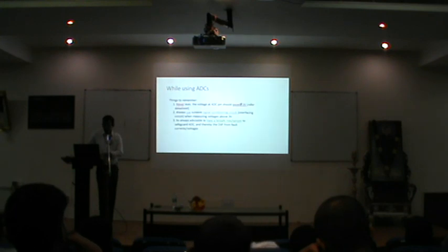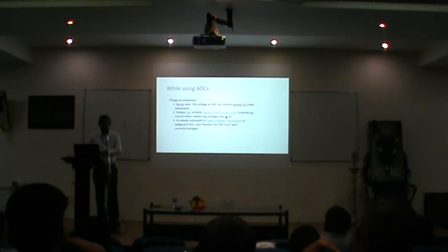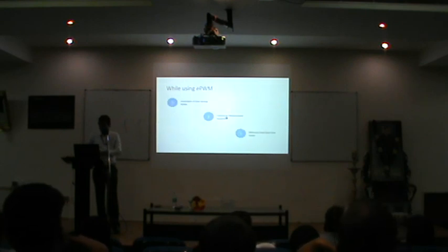Other things are known, whatever you have. Never exceed the voltage prescribed for the ADC pin. Use a signal conditioning circuit. Always have a fail-safe mechanism. Not necessarily will these signal conditioning circuits send a signal compatible with your ADC pin, so it is best to have a protection mechanism. The best, cheapest one is to use a Zener diode of appropriate value.